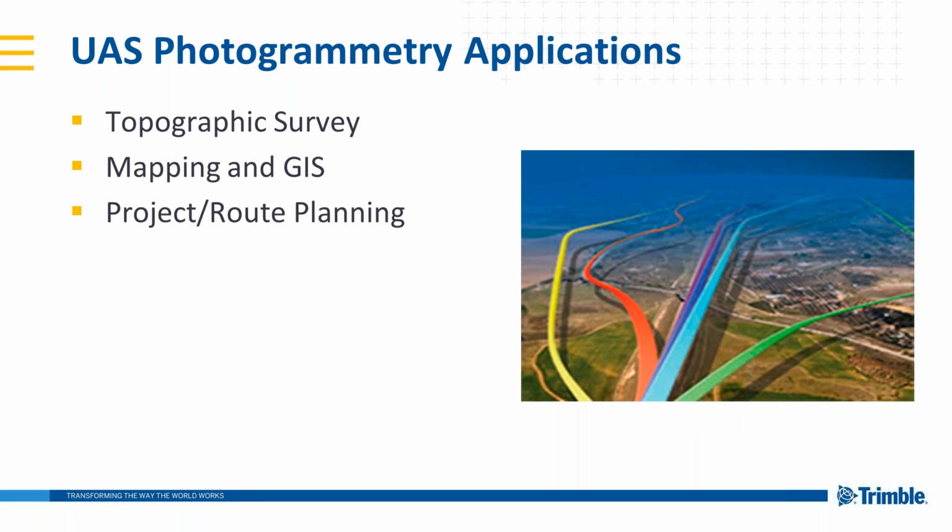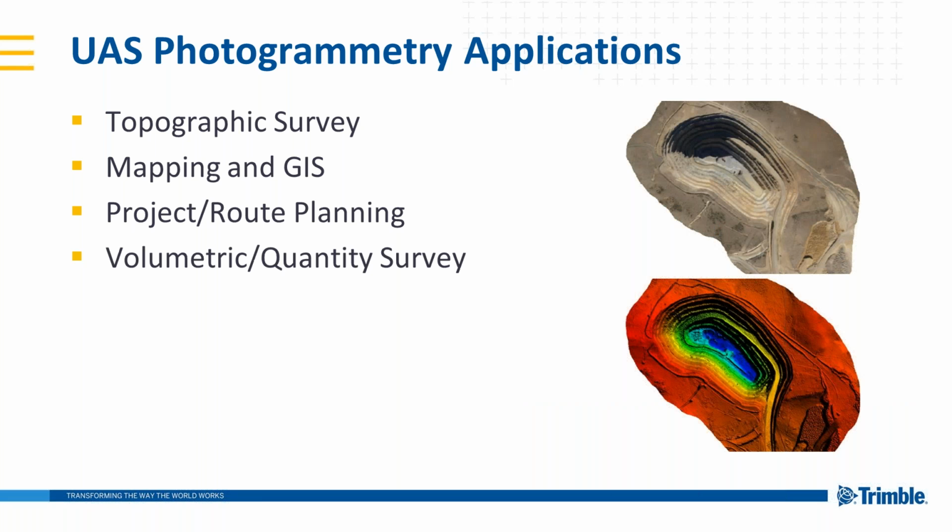Project and route planning, which is a really key element for UAS applications, as route planning generally takes long corridors, so it's not necessarily small projects. So UAS units are able to help with that long stretch of information, collecting that data in long strips. Volumetrics and quantity surveys.